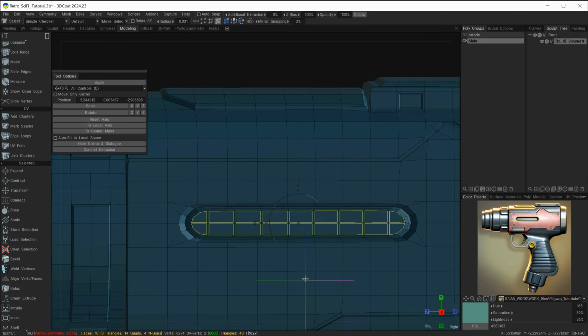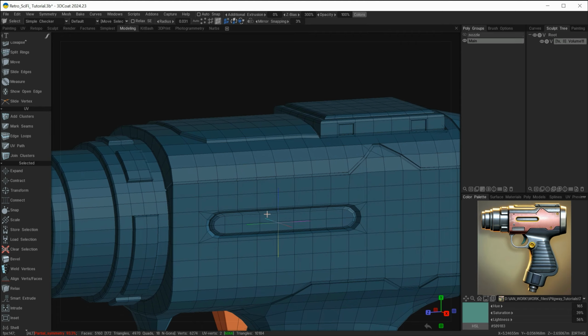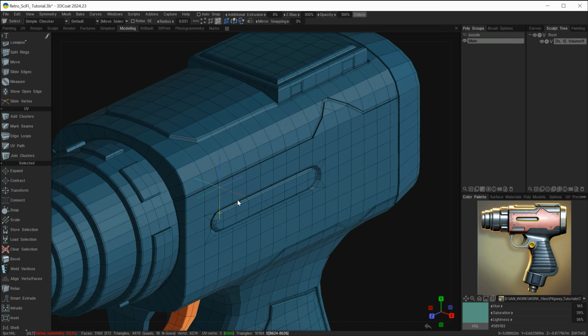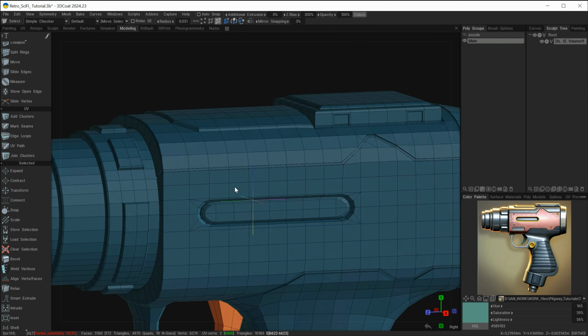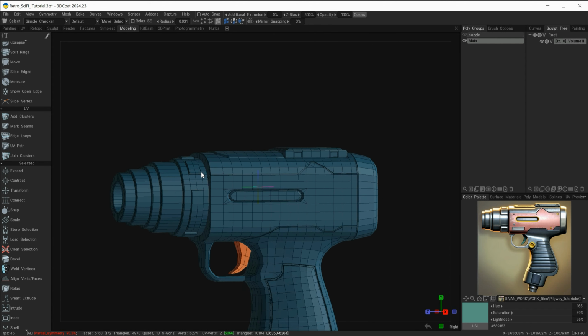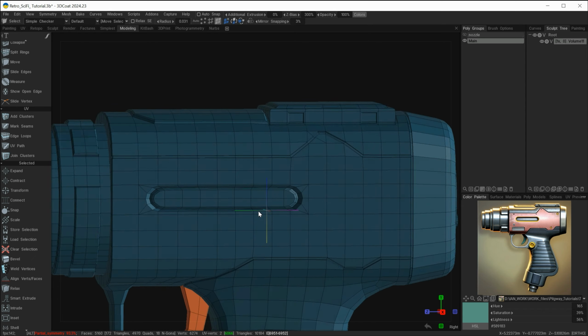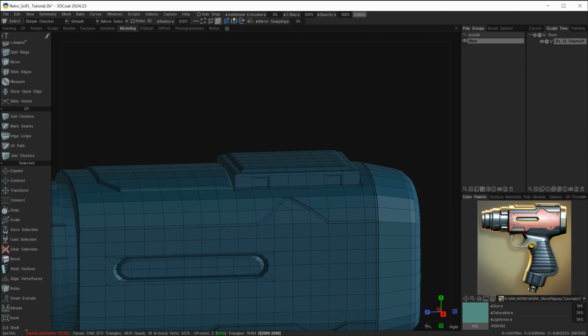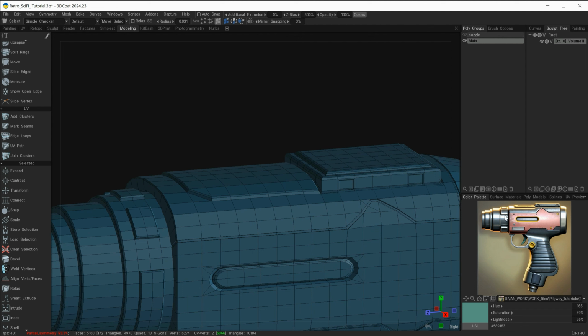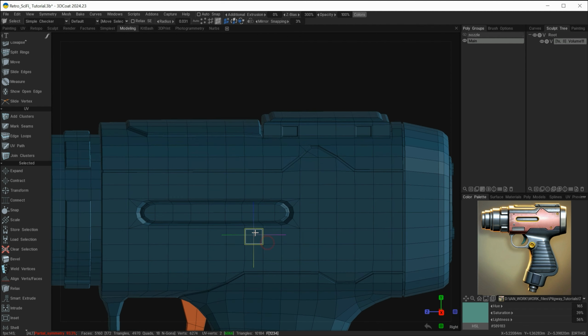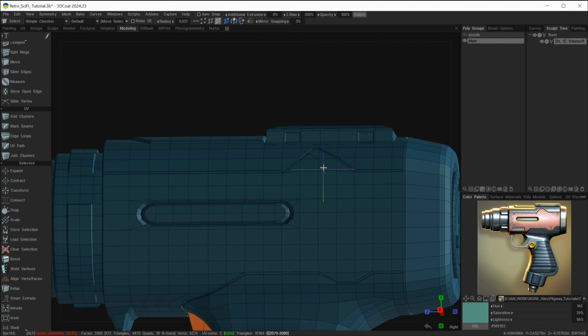Okay, so when we're looking at this now, we've completed all the main portions of our design, and we've used different techniques to create the extra details. Some of them, the majority of them, are just simple bevels and extrusions here. We're not really doing anything any more complex than that. The real difficulty here is choosing your selection and making sure that you have a selection that matches your reference in order to bevel and create these splits.